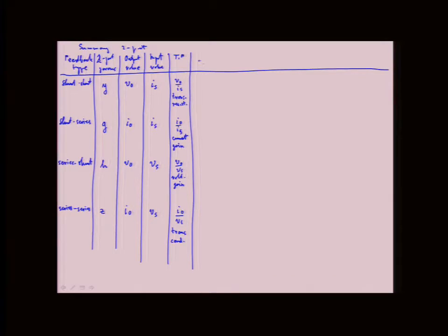Okay, so let's look at impedances. These are the ones that we labeled capital ZI for input, and ZO for output. These are closed loop. So in shunt-shunt, what is the value of the input impedance? Low or high? Yeah, in shunt, low. What's the value of output? Low.